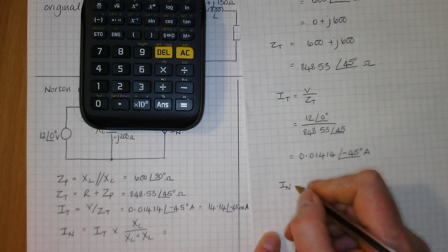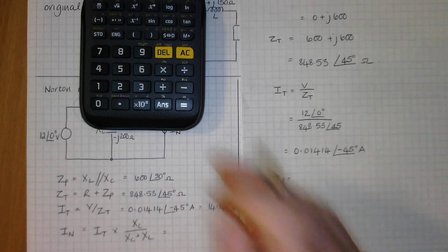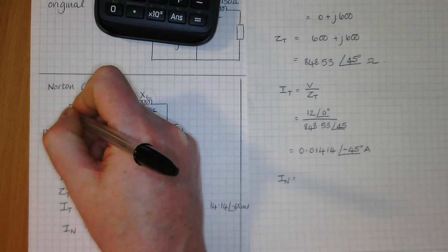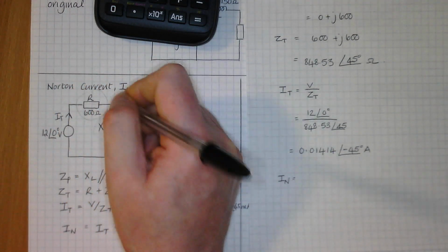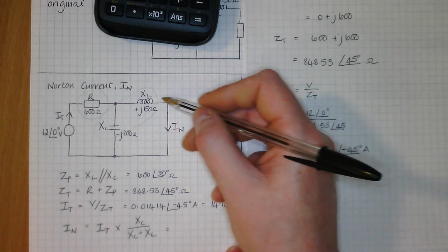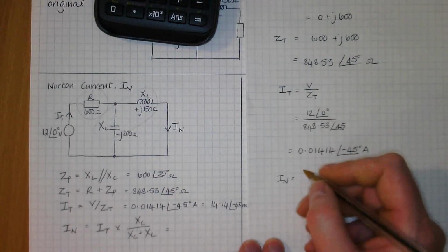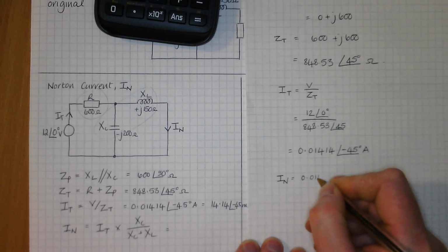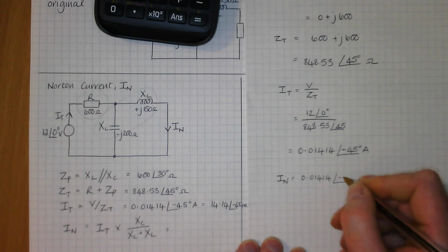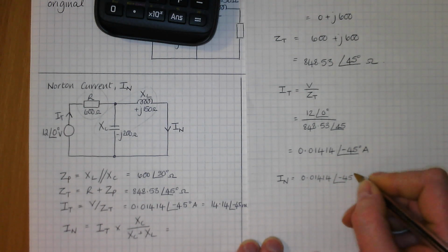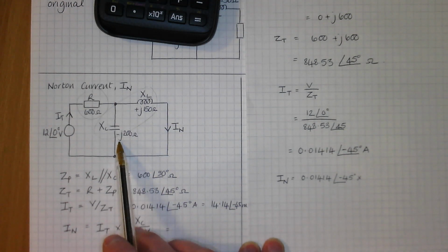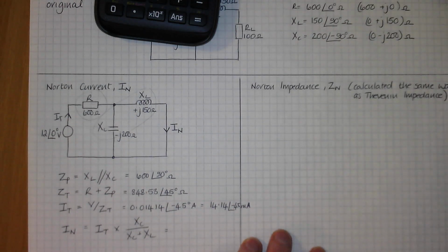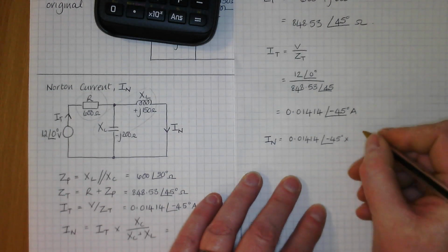And it's this current here that you're dividing. So that's your current here. It comes up round, hits that junction and then splits. So you want really the current flowing through this branch rather than the current flowing through that branch. So the opposite branch is always for a current divider, so it's that branch there. And because you're multiplying and dividing, you want that in polar form. So we've got that in polar form on our list, with that 200 at an angle of minus 90.